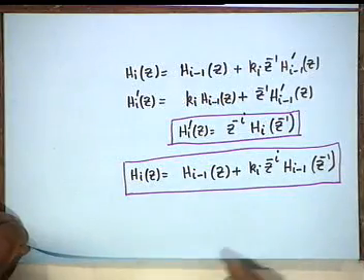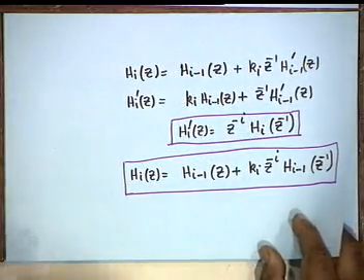So, we should proceed in the reverse direction. We should start from h_m and then successively, by an iterative method, derive the values of k_{m-1} up to k_1, because k_0 has already been made a short circuit. x_0 and x_0' are the same.